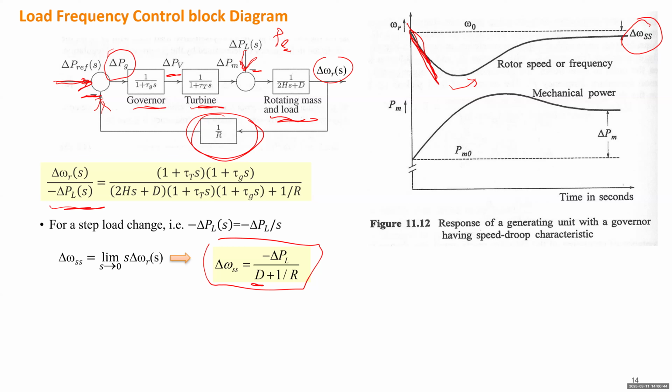Because if that delta omega increases, the feedback signal will be increased, right? Compared to the setup value, the valve opening will be increased. So then it will go in the opposite direction, trying to decrease that deviation. But the control value is proportionally depending on the variation. So in order to make this control function, the deviation has to be non-zero.